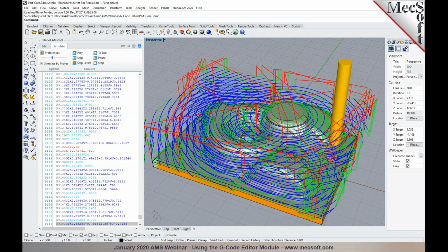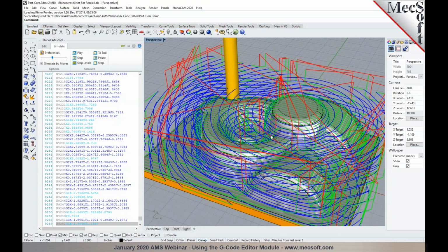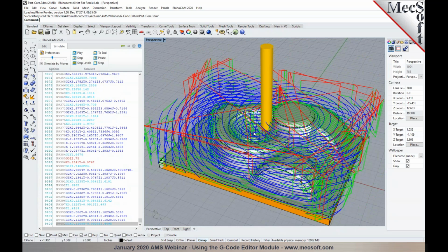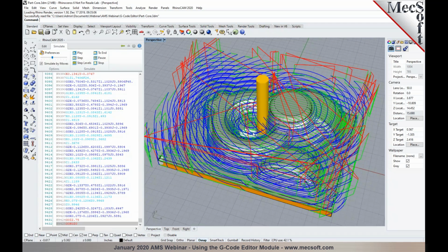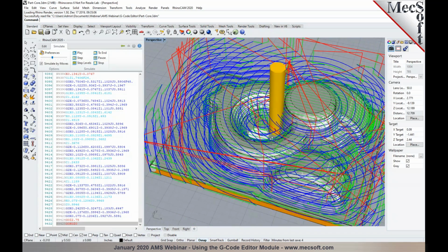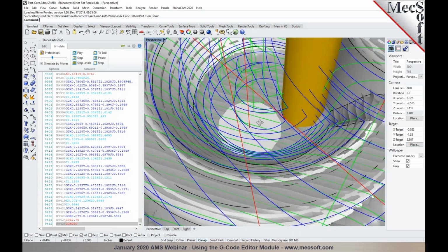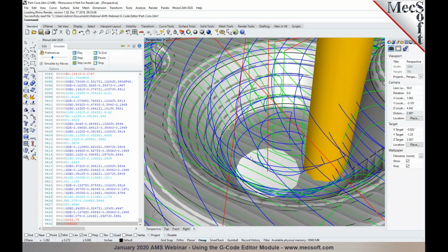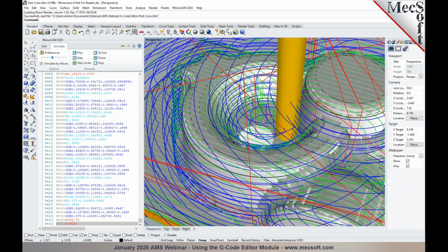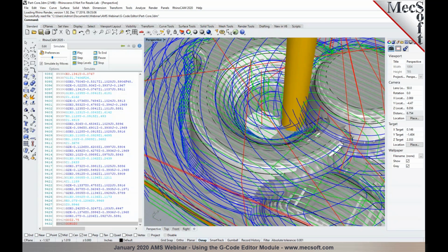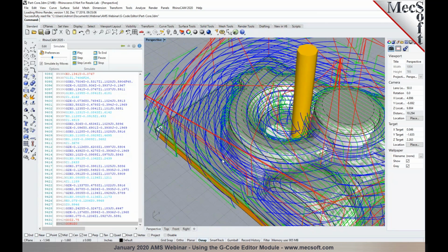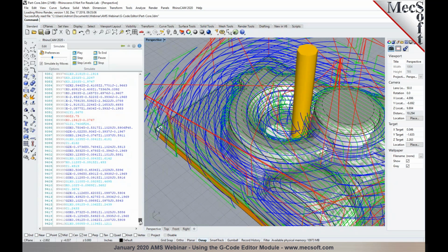And as it simulates the G-code, if you take a closer look at the cut material simulation, you will notice that the G-code shows a gouge on the simulated part, which we didn't notice in the simulation that we ran in our mill module. So it looks like something has been introduced in the G-code that's causing the tool to plunge down in Z to Z0.